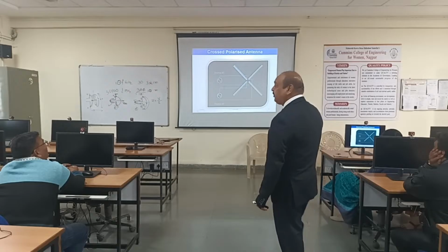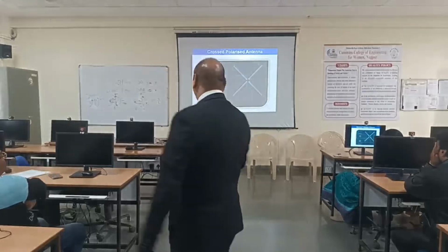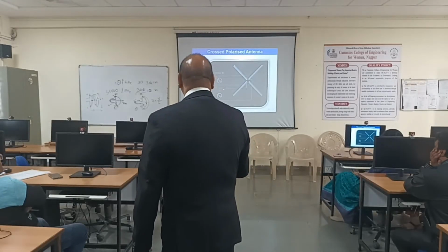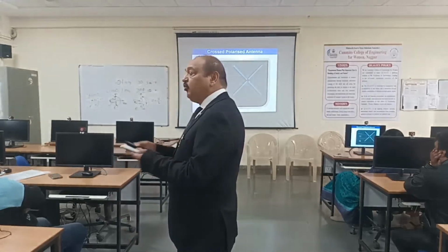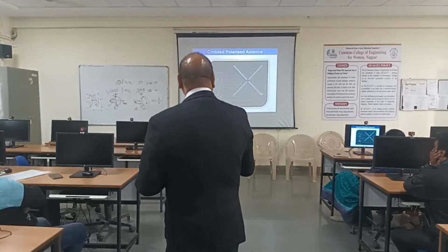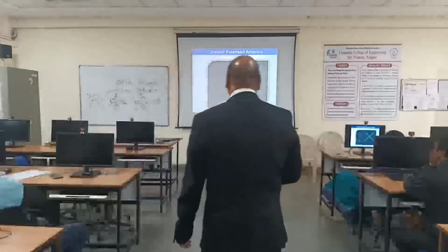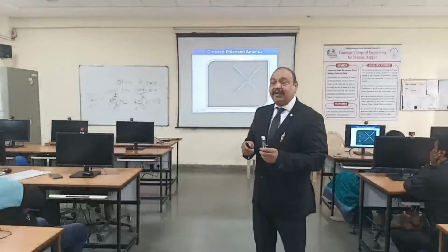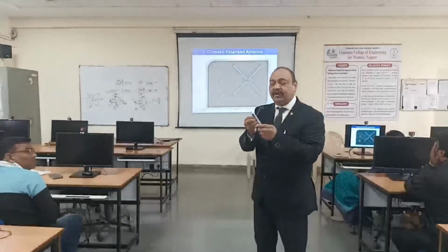So how do we connect these two antennas? We have to connect like this. This is the way it goes here. The other tap will come down here, and now this is the way it goes here. Accordingly, it gives one antenna structure. Let us take this antenna structure as horizontal and this one as vertical. It may be vice versa. Accordingly, you can get the cross polarization signal from the same antenna, which is placed in a cross. This is for horizontal and this is for vertical.